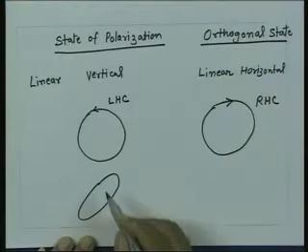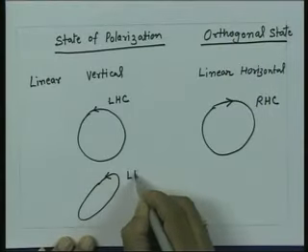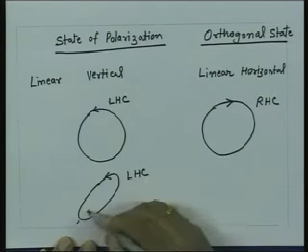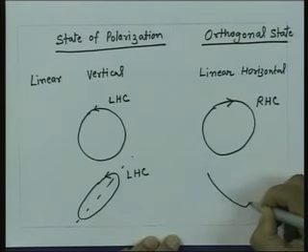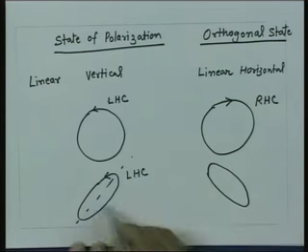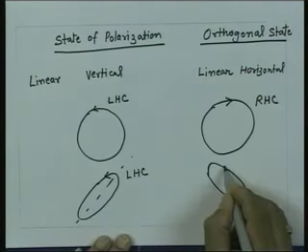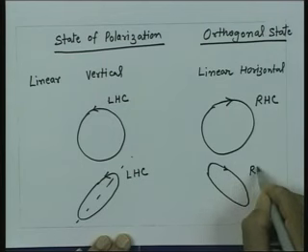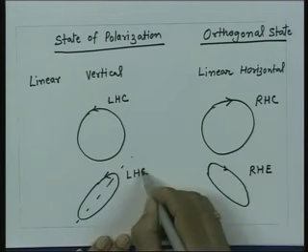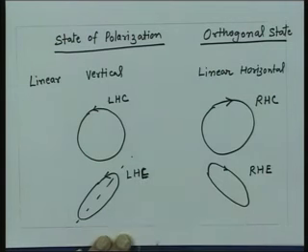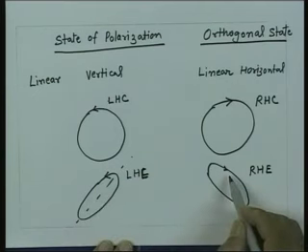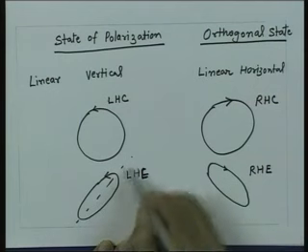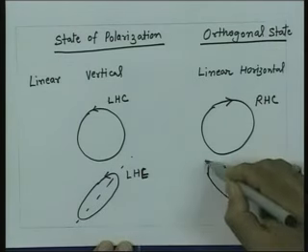So, if I take an ellipse which is like this, and if I say this is the left handed elliptical, this is the major axis now. If I take 90 degrees with respect to this, with the same ellipse, so the axial ratio is same for these two, the sense of rotation is opposite, so this becomes right handed elliptical here. So, for these two ellipses the axial ratio is same, the sense of rotation is opposite, and the tilt angle is changed by 90 degrees. These two represent the orthogonal states of polarization.